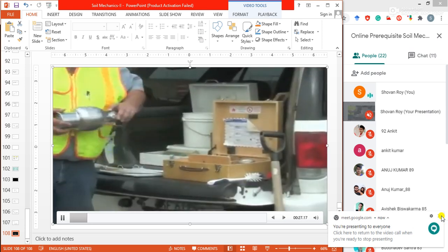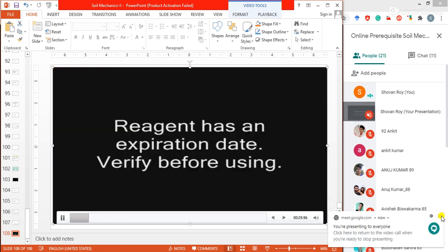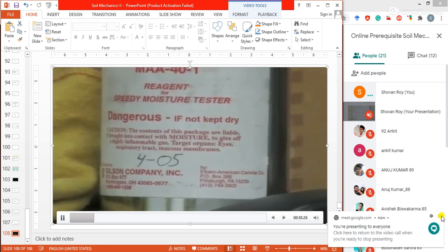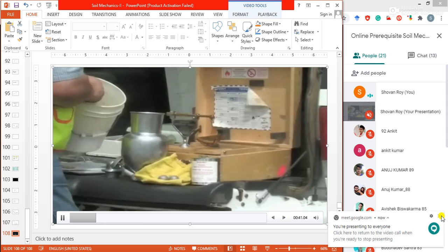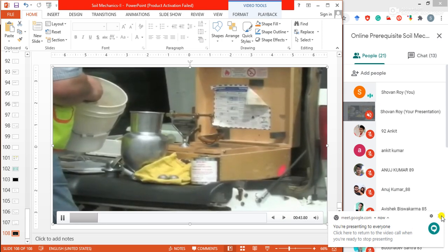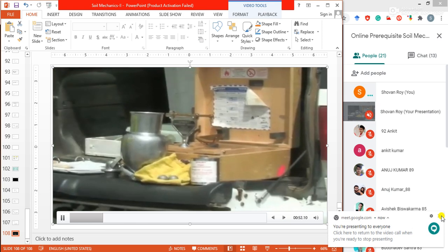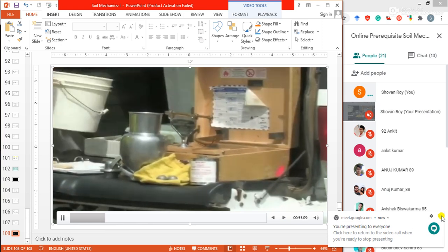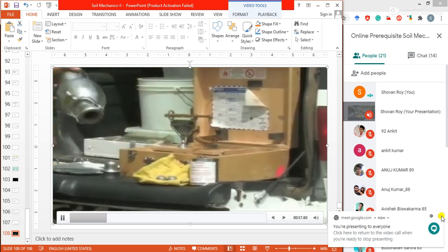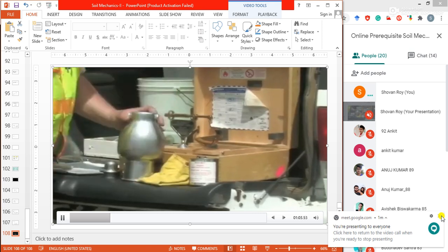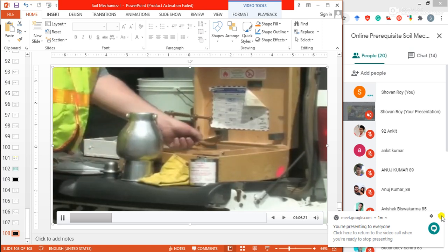In order for the test to be accurate, the calcium carbide reagent must be fresh. The shelf life is limited, so the date on the can should be checked to ensure the manufacturer's recommendations are met. Place the soil to be tested in the pan of the balance beam scale until the correct amount is present. The correct amount of material is determined when the red markings on the balance and beam coincide. Place the two steel balls inside the body of the tester and add the soil sample that has been weighed out.